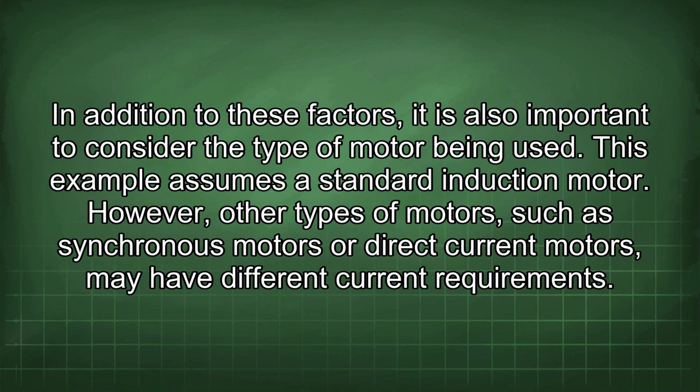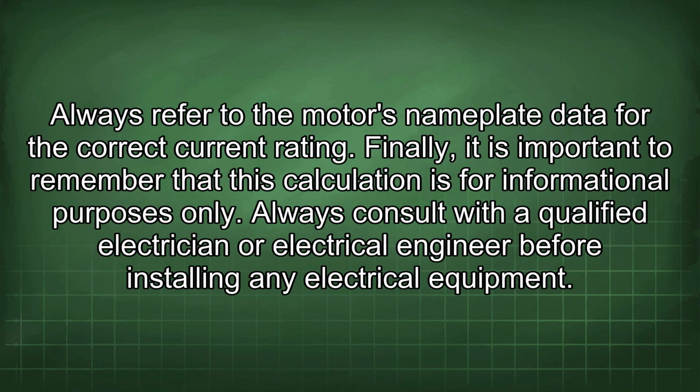In addition to these factors, it is also important to consider the type of motor being used. This example assumes a standard induction motor. However, other types of motors, such as synchronous motors or direct current motors, may have different current requirements. Always refer to the motor's nameplate data for the correct current rating.